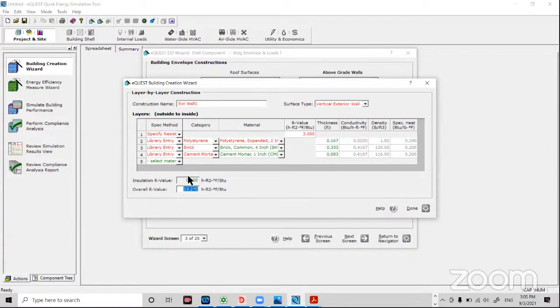Schematic design wizard gives the basic details. For example, you can rotate the building at the standard orientation like 90, 45, 180, 270. But if you want to rotate it, say 20 degree, 22.5 degree, that you can't rotate. But here, with this detail edit mode, yes, you can do that one. So when you have more details, you can go with design development. With minimum details, you can start with schematic design wizard. So I hope, Anurag, your doubt is clear.